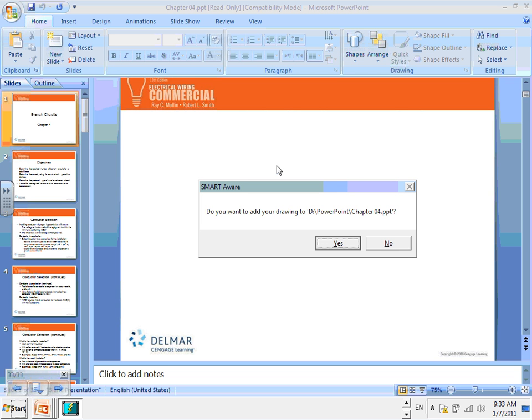Maybe that. Just because they have a cord and plug, say it's 30 amps, if that is a machine and you're going like 200 feet, you have to consider the voltage drop is calculated in there and everything else, just to make sure. You're still looking at that plug.